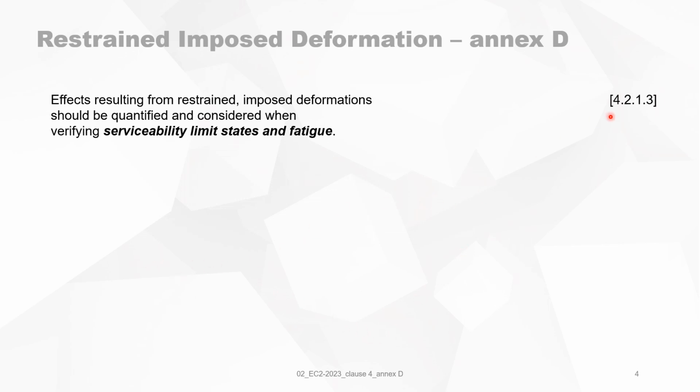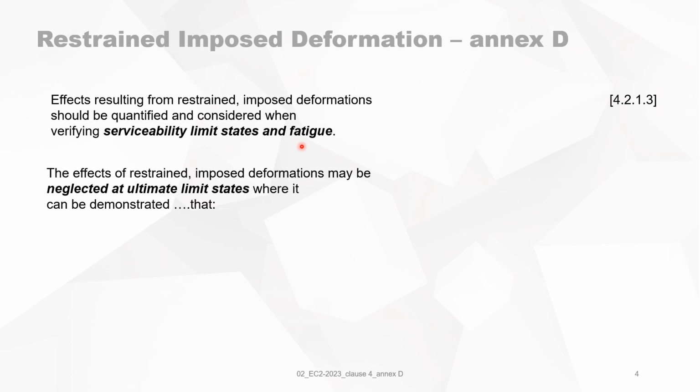Clause 4.2.1.3 states that the effects resulting from restraint imposed deformations should be quantified and considered when verifying serviceability limit state and fatigue. So this is for me very clear that restraint deformation is handled in SLS situation.